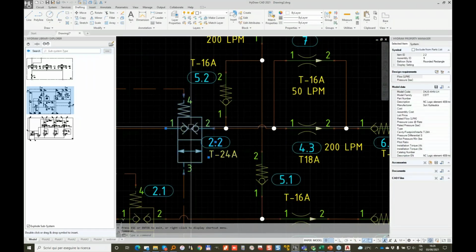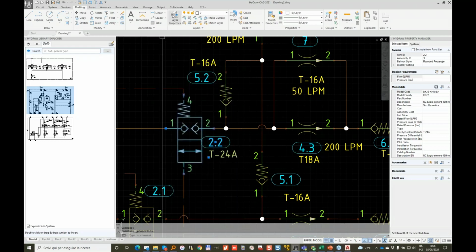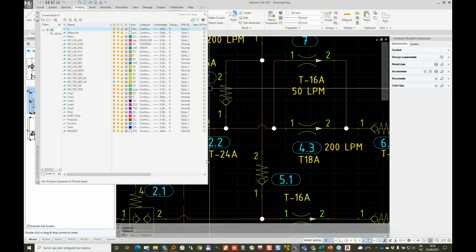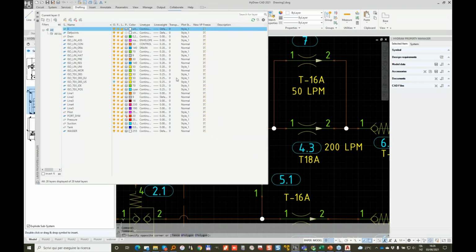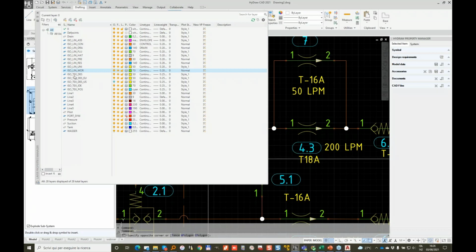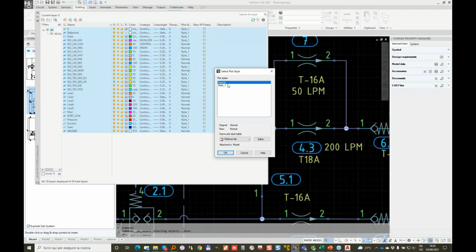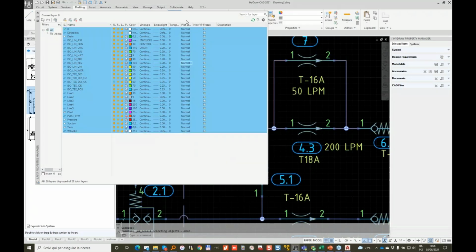Each entity in the drawing, when we click properties, has a plot style by layer. So it is controlled in this case by layer. So let's go to layer properties. And as you see, there are some layers set to normal and others set to style 1. So let's select all layers, and let's select normal for all. So normal, if you remember, was everything black and white.